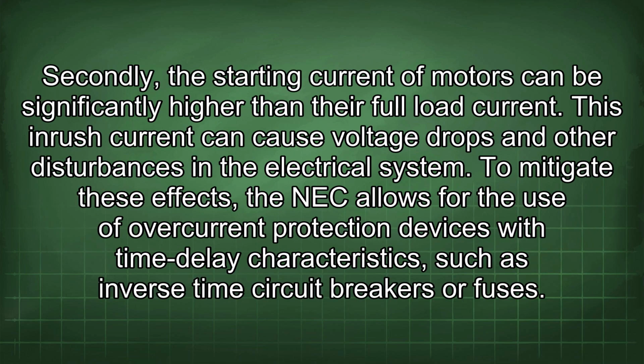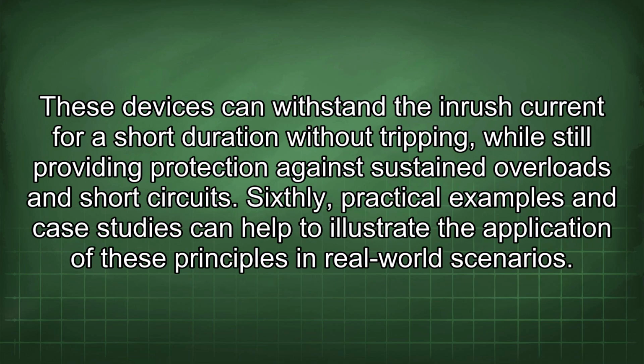Secondly, the starting current of motors can be significantly higher than their full load current. This inrush current can cause voltage drops and other disturbances in the electrical system. To mitigate these effects, the NEC allows for the use of overcurrent protection devices with time delay characteristics, such as inverse time circuit breakers or fuses. These devices can withstand the inrush current for a short duration without tripping, while still providing protection against sustained overloads